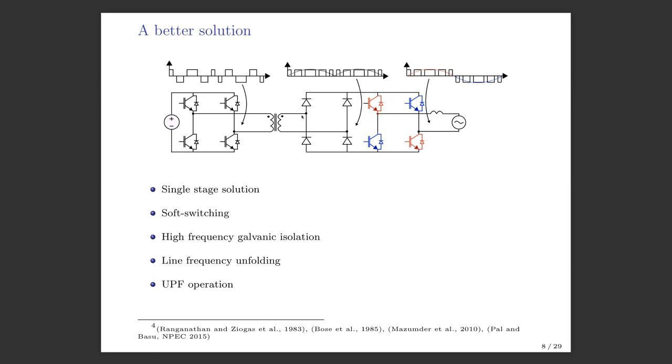And then there is a converter here, a cycloconverter, which will turn the high frequency AC to a low frequency AC. Though they did this work based on a resonant tank, this idea is very similar. Now, Professor B.K. Bose did some work very similar to this from 1985, and then Professor Sudeep Majumdar from IISc did a lot of work on this kind of topology with unidirectional and diode bridge around 2010. But this exact converter appears in one of our earlier papers from 2015.